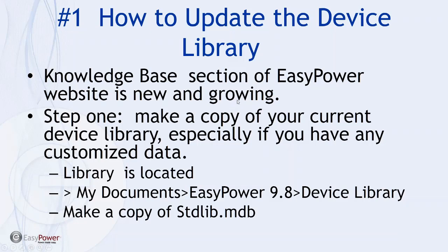And I'm going to show you that as I get through the PowerPoint. Step one is to make a copy of your current device library, especially if you have any customized data. And to do that, I want to show you where the library is located. It's under My Documents, EasyPower 9.8 Device Library.